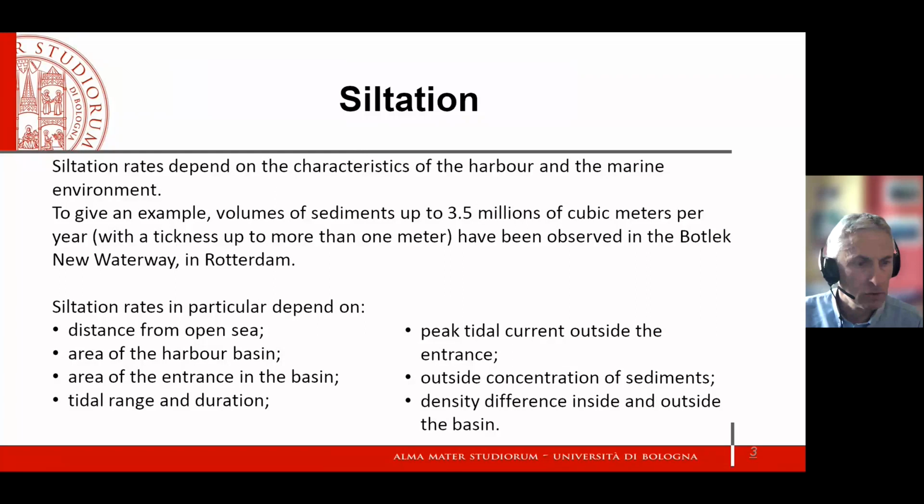Siltation rates depend on several specific features, and in particular, as you can see in the slide, distance from the open sea, area of the harbor basin, area of the entrance in the basin, of course, tidal range and duration, because the dynamics of tides, the evolution of tides and the recession of tides causes fluxes of salt water inside and outside the harbor basin.